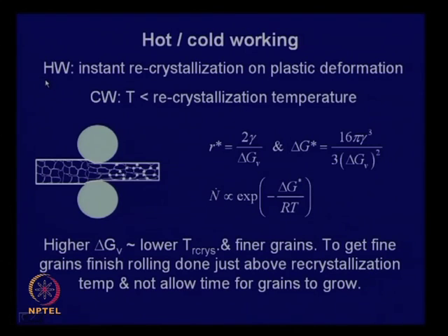Now, more technically, in hot working you have instant recrystallization on plastic deformation. But about this recrystallization temperature, it is not a definite fixed temperature.